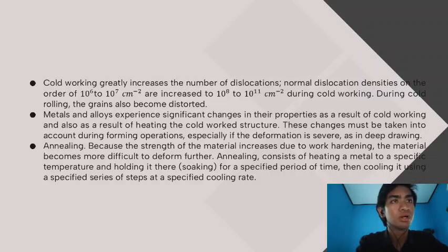Primary uses of annealing include softening metal before or during the fabrication process. Annealing is used as an intermediate step in the cold working process to reduce the internal stress in the material and increase its ductility so that it can undergo further cold working without introducing macroscopic defects such as cracks.